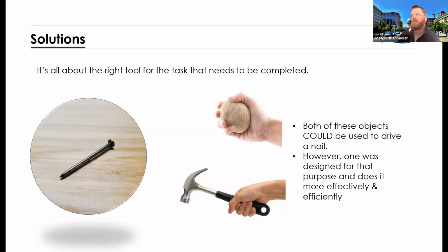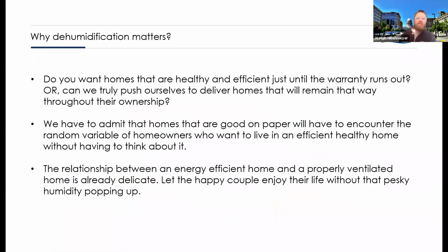You need that high airflow and you need that ability to condition the air before you deliver it to the space. And a couple other points on why I think dehumidification matters is, we don't just want these homes, I believe, to be healthy and efficient until the warranty runs out or after the first year. We want homes with good bones and good lungs. And having a system in place to manage that excess humidity for the times when it does get high, maybe that's far out from the time that the people purchase the home, but it's still going to be important. Why should they have to go buy a dehumidifier from a retail environment later if the home would be better served by having one now?